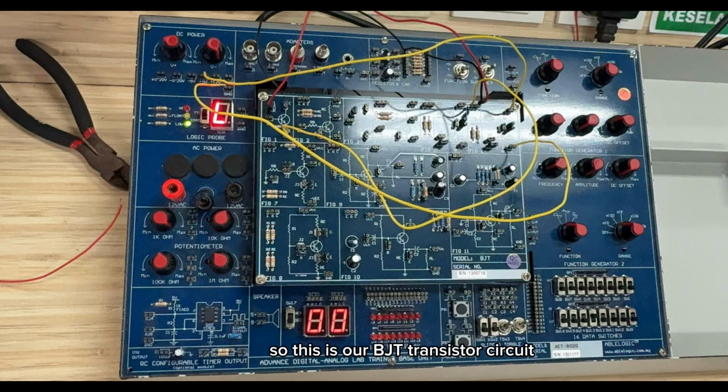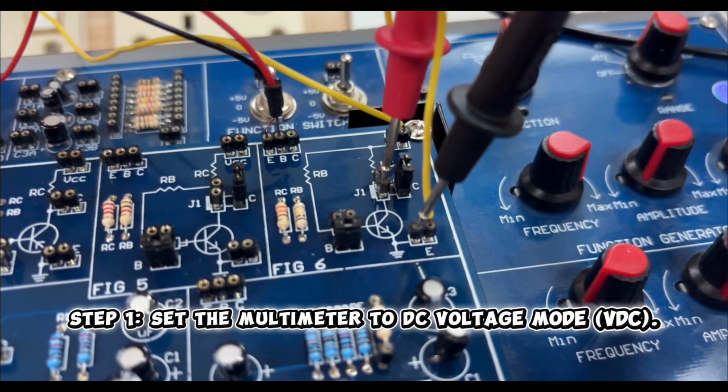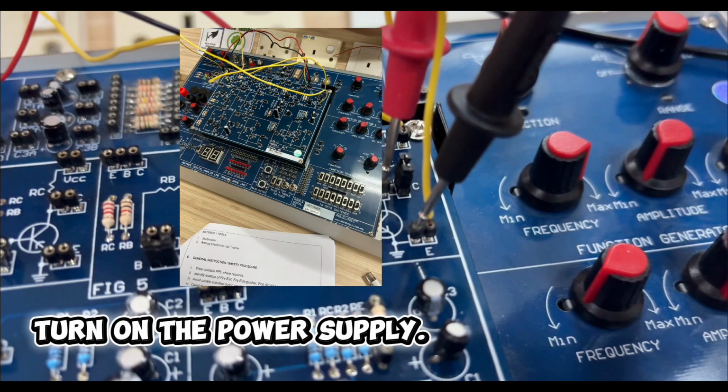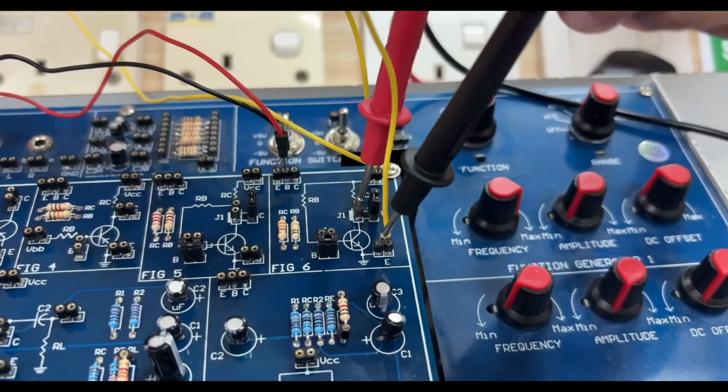So this is our BJT transistor circuit. Next, I will explain the step-by-step procedure to measure voltage and current in the BJT circuit. The first step is to set the multimeter to DC voltage mode. Connect the black probe at E, the negative probe, and the positive probe at C. To measure the voltage, we need to turn on the power supply and record the voltage reading, as in the video recorded.